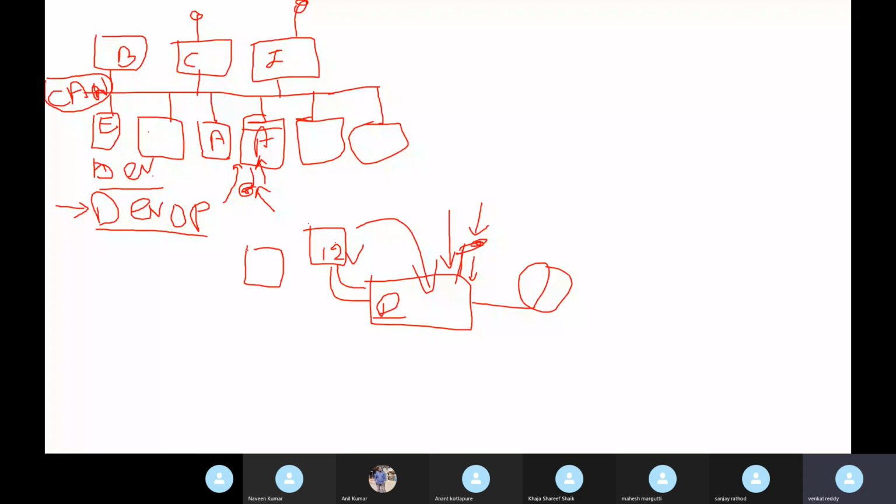Since we are working in the lab, we don't have the sensors, because these sensors are available in the car but not in our lab. So instead of that, we will use a software called CANoe. In this CANoe, signals related to this crash zone sensor will be available. We will send these signals from the CANoe software.